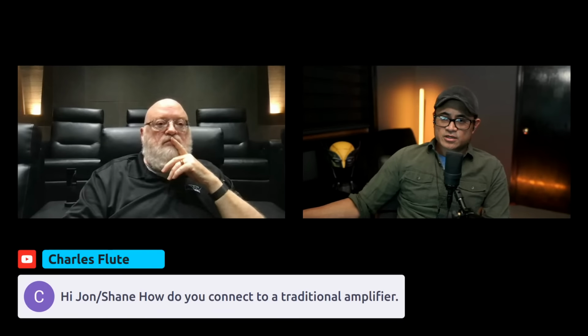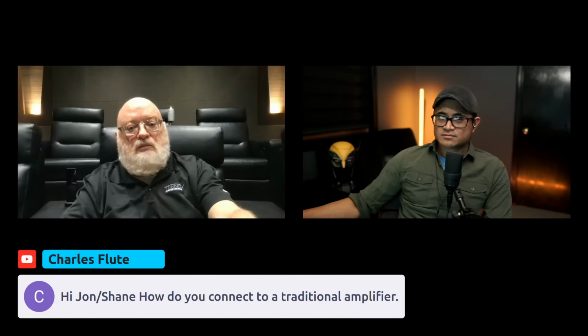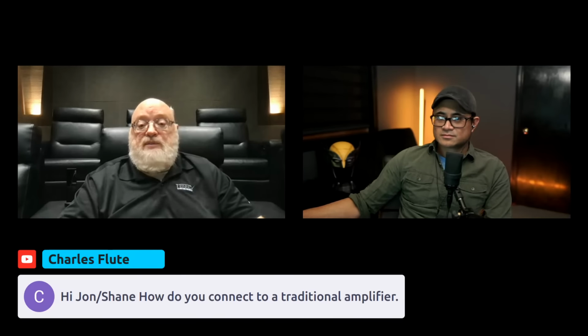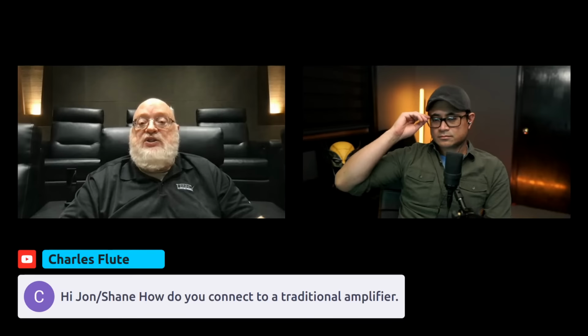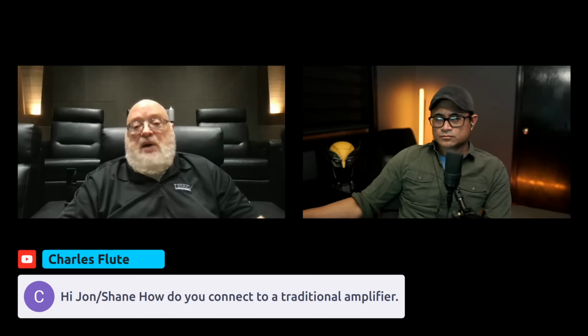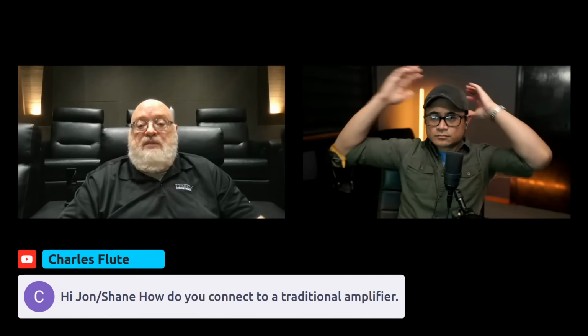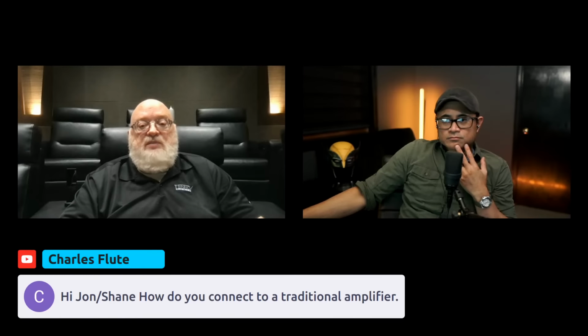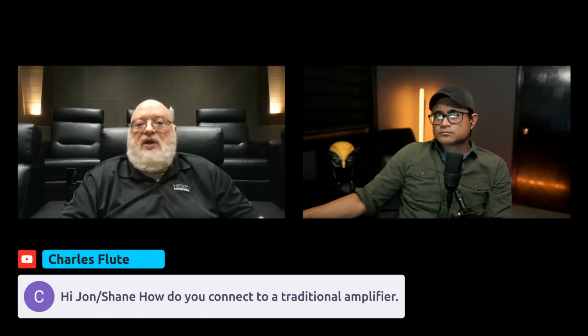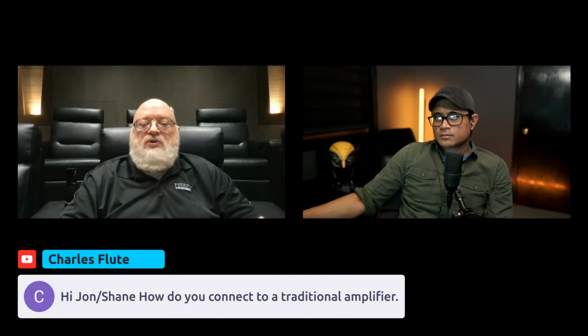Hi John, Shane. How do you connect a traditional amplifier to the CI? With the analog outputs. If you have more than 8 channels that you need to do that with, you would have to buy external DA converters, because remember, the original idea of this piece was that it was going to be all digital. And we did add the 8 analog outputs for whatever you want to use them for. We were thinking partly, if people want to use it for a bunch of subwoofers for waveforming, they're probably going to need analog outputs. So we wanted to include those, but they're not specific to subs. You can use them for anything you want.